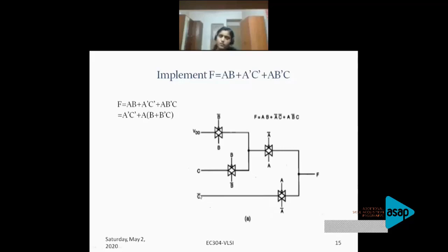That is your wish. If you want to choose here as A bar, then this will be C bar. So here the input I've chosen as C bar and the gate I've chosen as A bar. So the output is nothing but C bar A bar, plus A into B bar, sorry, A into B plus B bar C. So if you look here, this is C multiplied by B bar, so this is C B bar or B bar C, this term plus B.